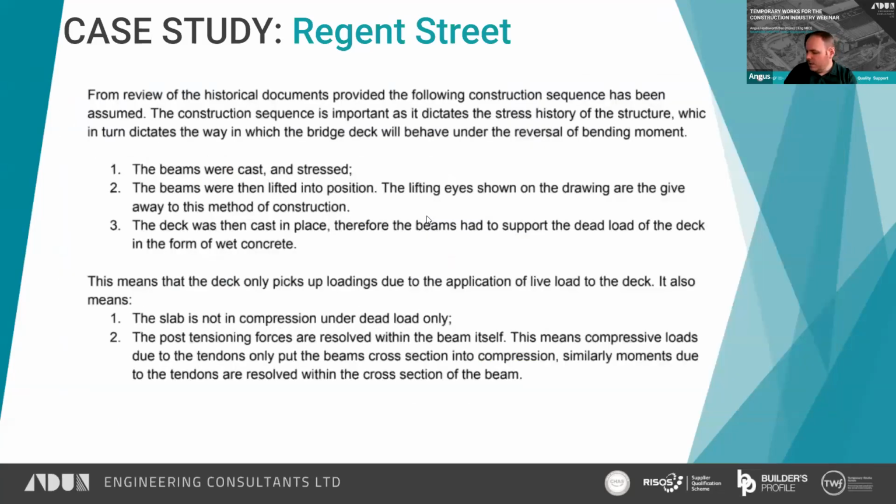So again, it's a concept you don't hear very often, or don't hear being discussed very often, but it makes a big difference as to how a structure works and how it's going to behave. So by going through the historical drawings and everything we could find, our understanding of the construction was that the post-tension beams were constructed, stressed, and then they were lifted into position. The supporting information for this was the lifting eyes and the fact it didn't really work if you just picked it up without the post-tensioning.